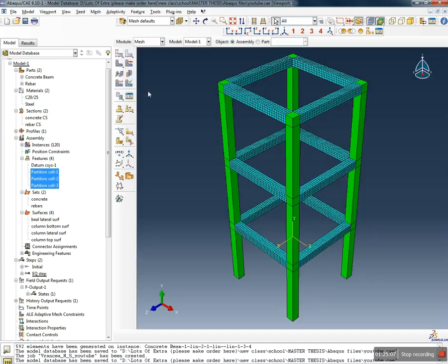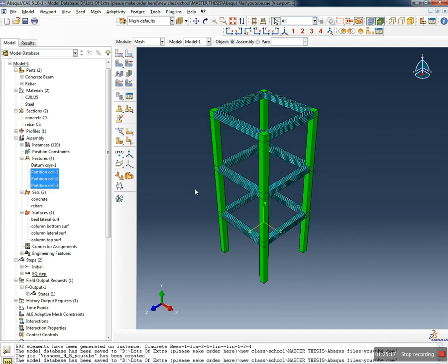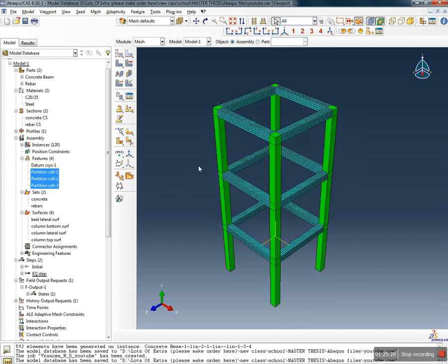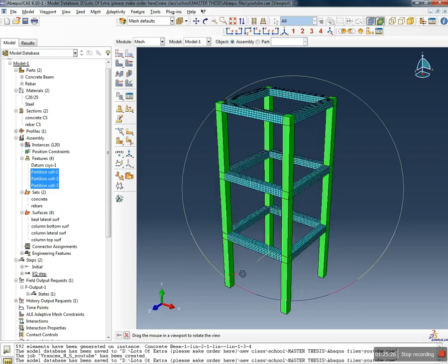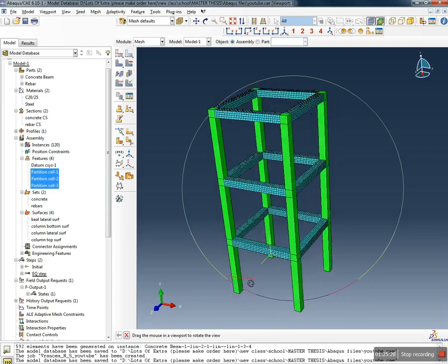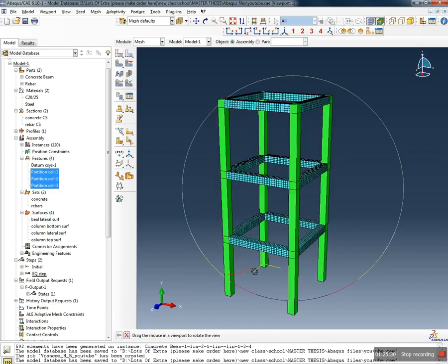I go to the mesh again, see if all looks right. So it doesn't look right because we introduced that. So for some reason, before doing our meshing, these partition planes got suppressed here. So pay attention before doing your meshing that you have your partition planes, so you don't get something like that, right?